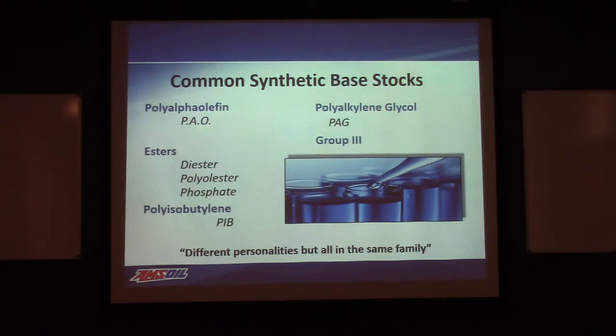We see esters. There could be a whole variety of esters: dibasic acid esters, polyol esters, phosphated esters, okay? They can be used in a number of different things. Phosphated esters are really, really popular when you're dealing with concerns regarding fire hazards or an explosive atmosphere. They tend to be used in situations where an explosion or a fire hazard could be a major concern. Underground mining would be one example of that.